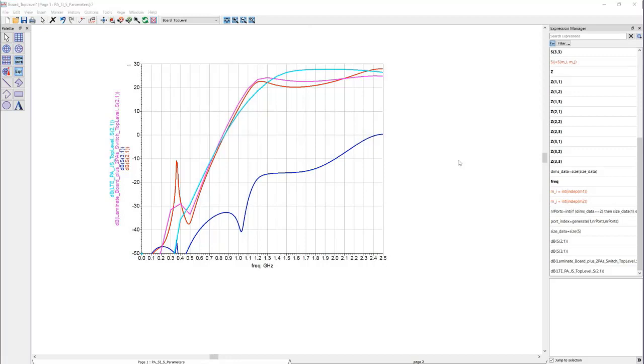You will see later, I will even verify it for you by just adding a 0.8 nanohenry inductor at the drain DC bias line on the MMIC PA alone to replicate the effect of the bond wire. And now, with added solder bumps and bias lines included, it resulted in an even larger effect and increased the size of that spike. So one clue we are getting out of this is the DC bias at the drain needs to be better isolated from RF at the PA level.